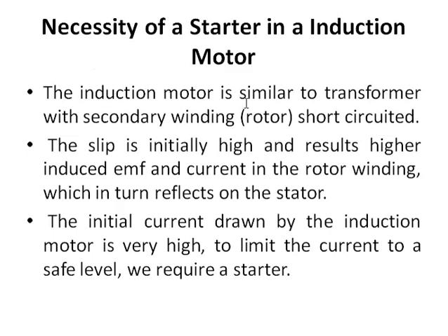The induction motor is similar to a transformer with the secondary winding, that is the rotor winding, short circuited. We have already seen the construction of the induction motor. We have a stator winding on the stator part, and on the rotor part we have the rotor winding, and when a three-phase supply is given to the stator winding, it creates a magnetic field, and that magnetic field gets linked with the rotor winding.